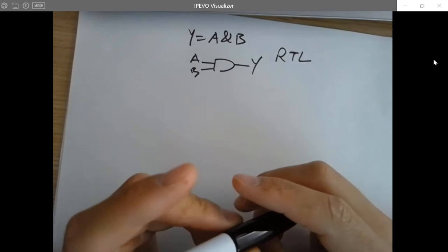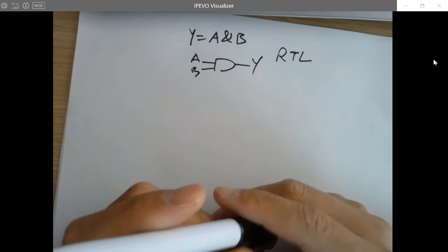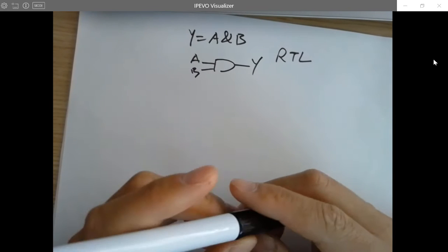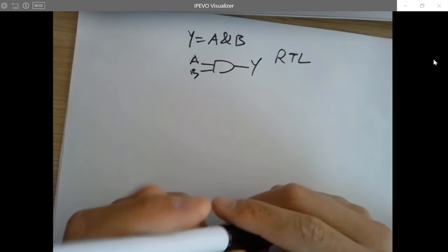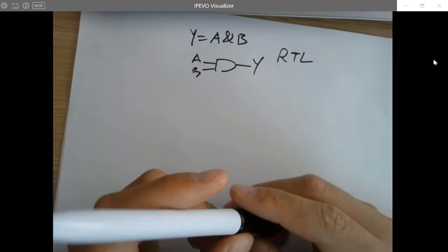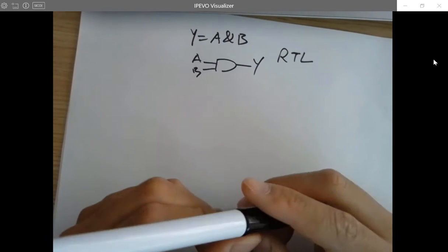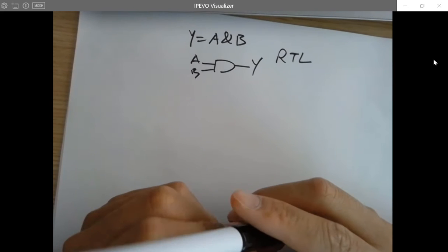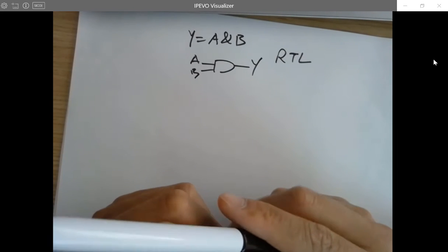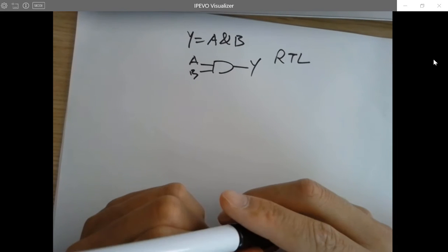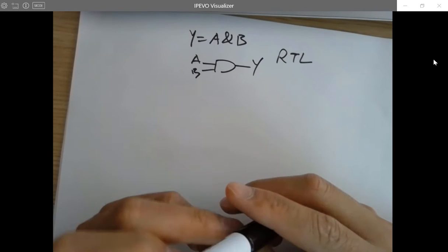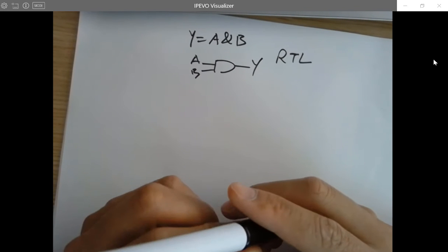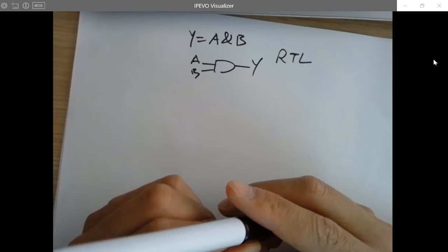But however, that's a design strategy. Because we want the CPU to run faster, that's why we need a smaller technology. And it's going to be 20, 40 nanometers. We want the CPU to run faster. And so that's why we cannot keep the flash on chip. So it has to be off the chip. And so we need to read the program from the flash every time we run it, so it knows what to do.